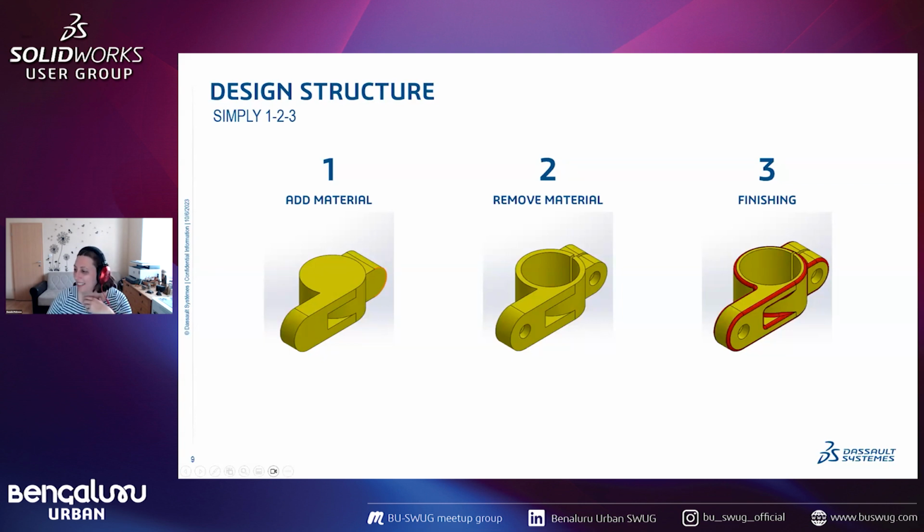It's not a question, but I've seen many people do this. As soon as they think that they need to apply the fillet somewhere, they'll just do it right away. Generally what everyone does is they apply the fillet at the end of the design. I mean, it's better to give fillets at the end of your design. But what I've seen is some people, as soon as the feature is done, apply the fillets right away, and then they struggle to edit their parts afterwards. So what suggestion would you give on why people should always give the fillets or drafts at the end of the design?